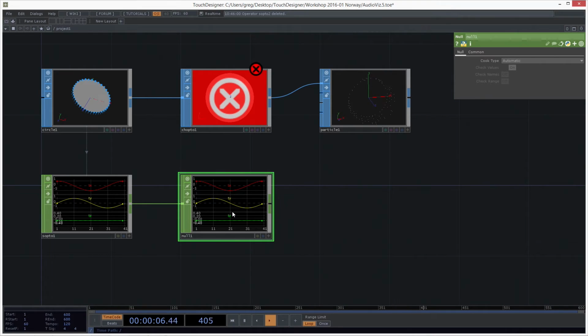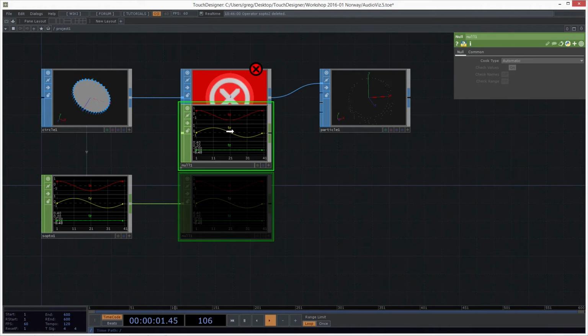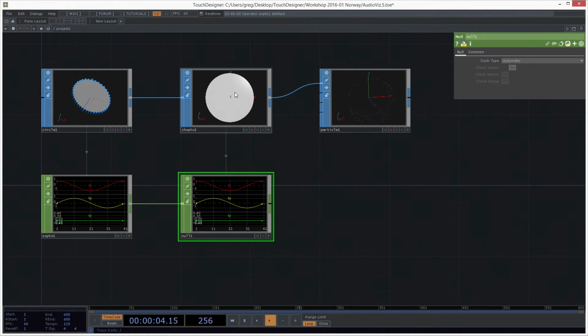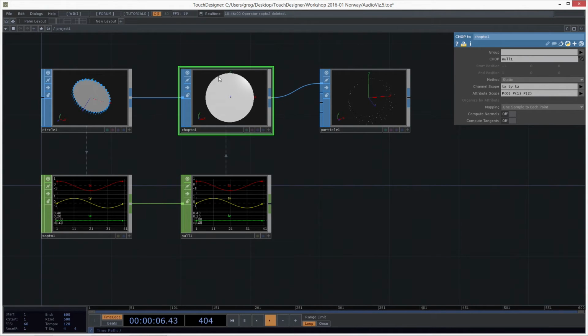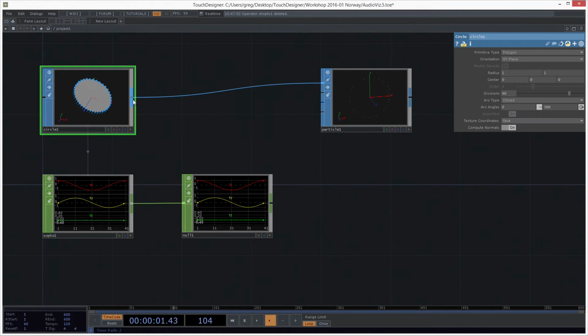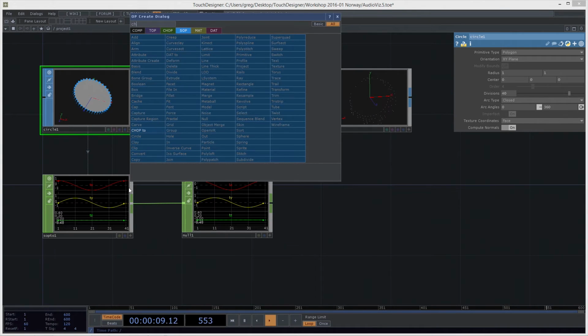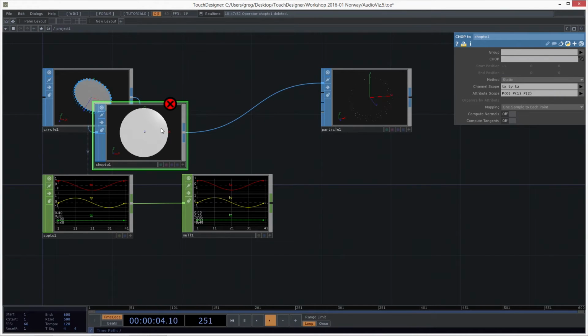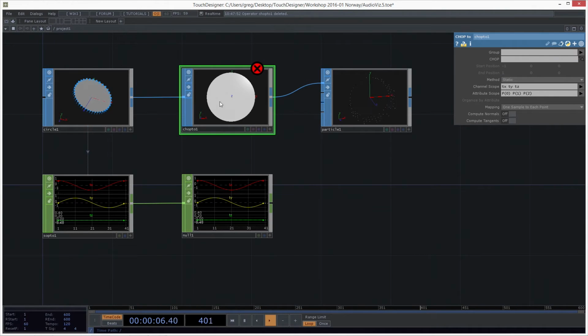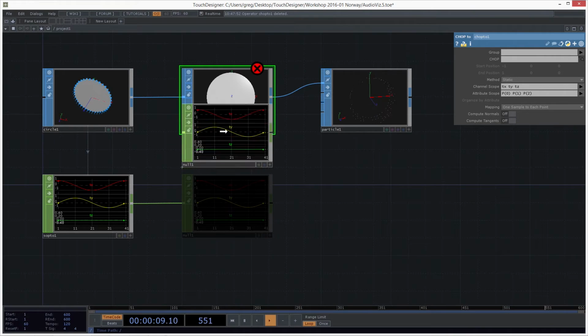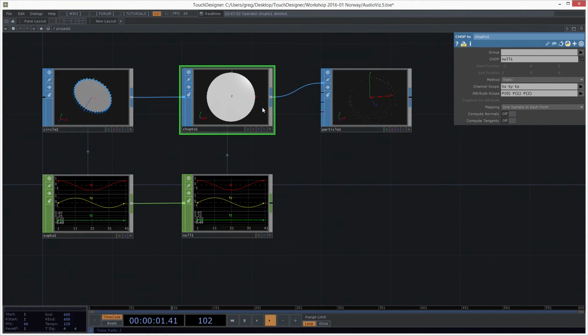And now we probably can do it exactly this way as we just discussed. We can take the null one and just drag it onto the chop2. If you right-click on the output of the circle, and then type chop, ch already brings up only the chop2. Then hit enter, and you get the node. And then drag the null one onto it, and it fills it in.